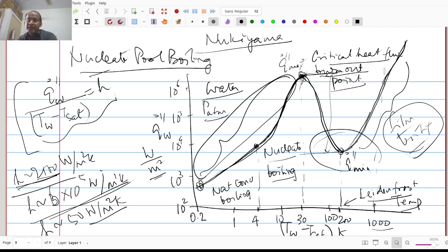the temperature of the wall went beyond the saturation temperature. So water saturation temperature is like 373 Kelvin or 100 degrees Celsius, and if the temperature goes about 1000 degrees beyond that, so it's about 1100 degrees Celsius, the heater material he was initially using, nichrome, would melt at temperatures under 1100 degrees Celsius, and therefore he would not have the heater continuing to heat this.